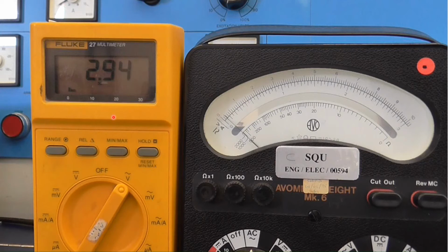Only one point you need to take care of is that once we start increasing the voltage, we have to go in one direction, forward direction only. If we want to go to 10 volt and by mistake we go to 12 or 13, we cannot go back, we cannot decrease it, otherwise we will have high stresses error. So we have to go only in one direction till we finish. So we just take the reading which occurs there. Okay, let's start.